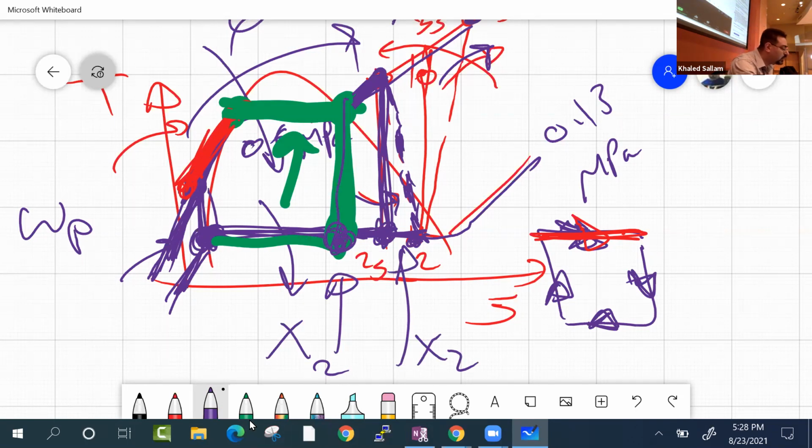It means that at the end of the turbine, when the turbine finishes its job, the last row of blades will have a lot of droplets, right? If you end up here, this is dry, maybe one droplet or two. The velocity inside this turbine is so fast, and if you have droplets on them moving at very high velocity, they will be like bullets. So a turbine running that wet will not last that long.